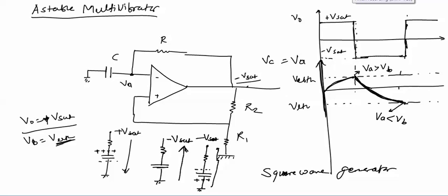In this square wave generator, one cycle is completed here, or this is the starting part of the waveform. So when it goes to minus Vsat again, this is one cycle of the output waveform. In this output waveform, if the capacitor charges and discharges fast, then curves will be like this.